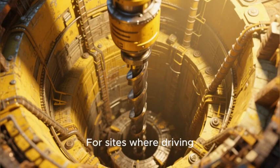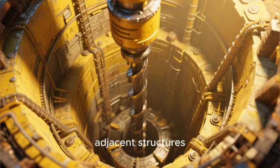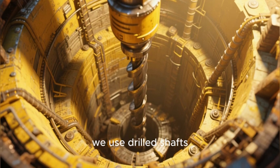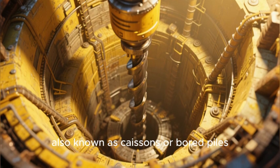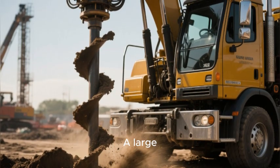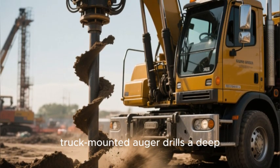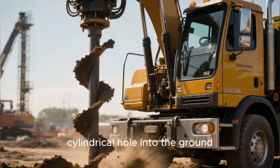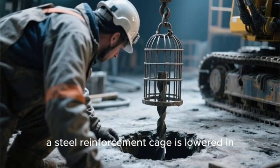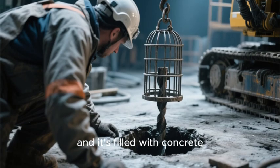For sites where driving vibrations would damage adjacent structures, or where the depth to bedrock is extreme, we use drilled shafts, also known as caissons or bored piles. This is a clean hole method. A large, truck-mounted auger drills a deep cylindrical hole into the ground. The hole is then inspected. A steel reinforcement cage is lowered in, and it's filled with concrete.